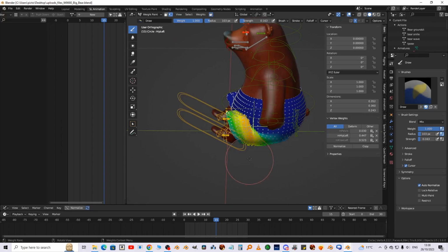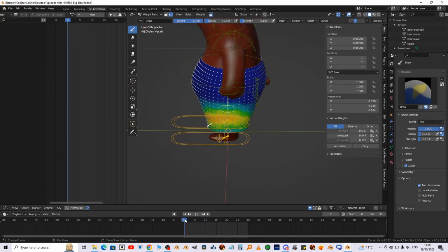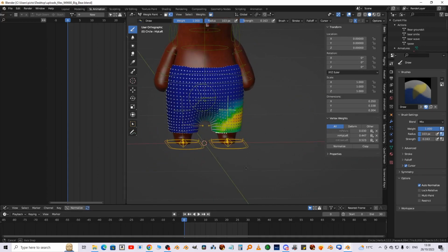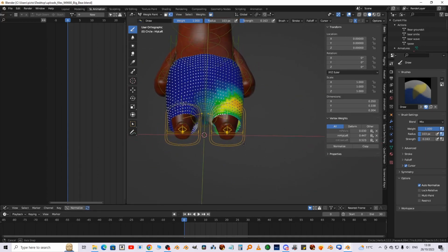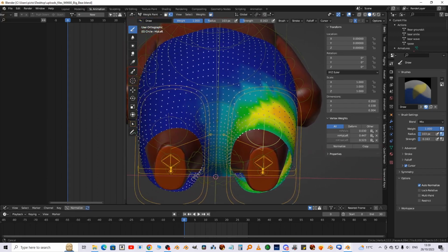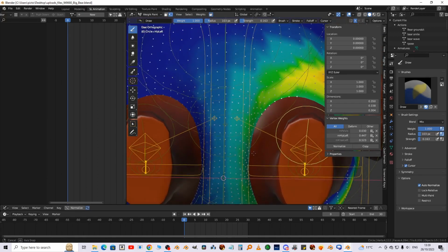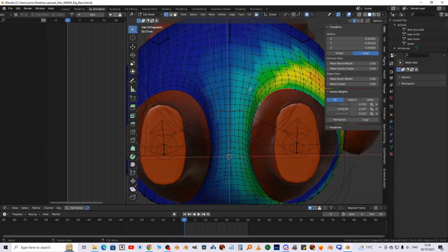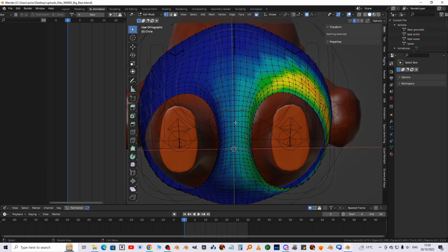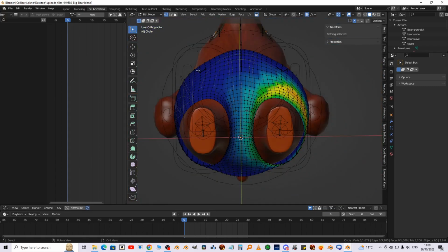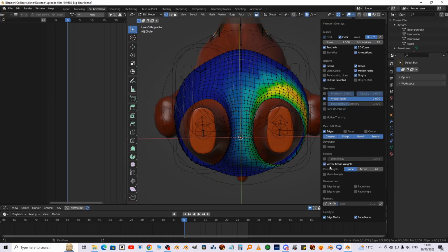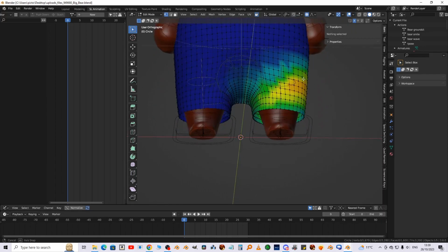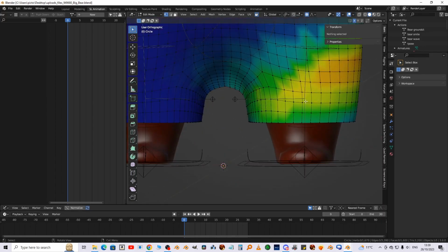So I'm just going to move the slider to 0. And we'll select those problem vertices underneath. Go back to edit mode. Click away. Now this is coloured in edit mode because I've got vertex group weights ticked in overlays. That's handy for visualising in edit mode.